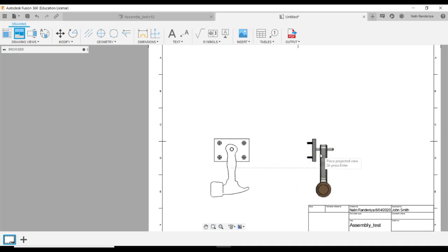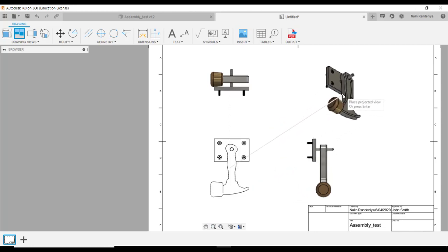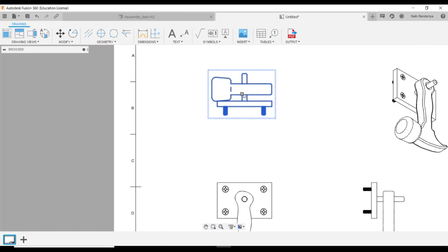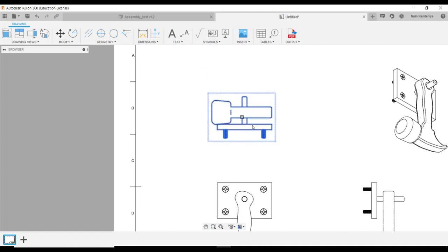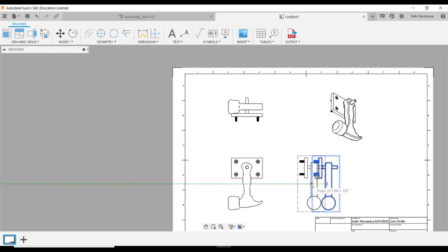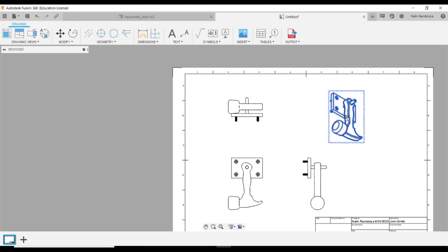Okay, so I'll go this side and also top view. There you go. And also one isometric as well. There it is. So once you finish with that, press the escape key and you're done. You can move them, just simply click on that. There will be a box appearing in the middle. You can move them. Notice these perpendicular views, you can only move along that axis because they maintain that relationship, that projection. Notice here, that's all you can do.